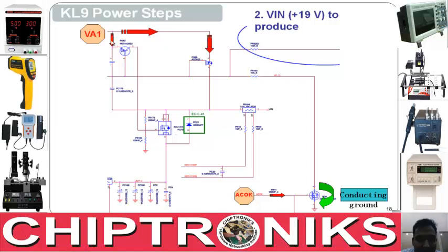path, right? This will provide a path to go over here, because ground has shifted now over here. If it conducts current, this will be at ground, so this point will also be ground, and this point will also be ground, so it will give a path to flow from here, right? Here it's a transistor, all right? In a transistor, if the voltage at the emitter is greater than the voltage at the base by 0.6 or 0.7 volt, then the transistor is in saturation mode.